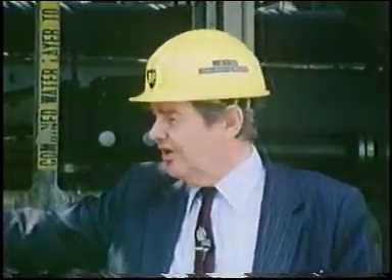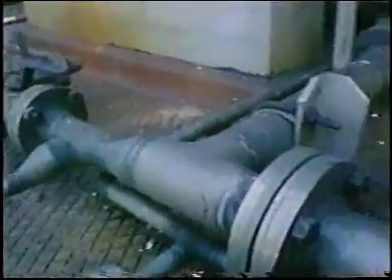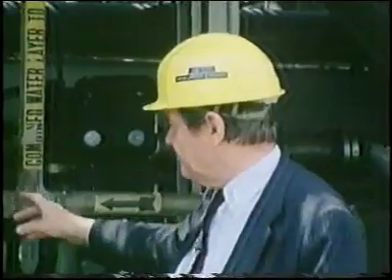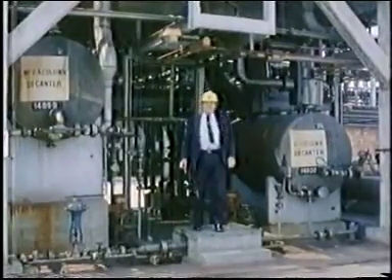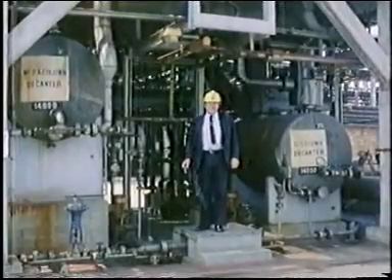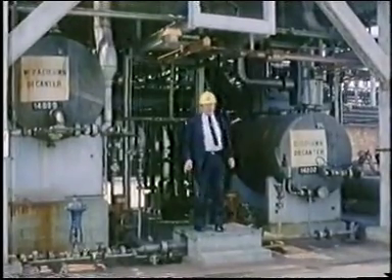The lower aqueous layer, with a few percent of ester and alcohol in it, is pumped away along these pipes to a distillation column in the next structure to recover the ethyl alcohol, which passes back to the reaction system. The upper ester layer, containing about 5% of water, is pumped by a pump at the back, a portion of it going back to the top of the distillation column to suppress acid distilling, and at the same time to remove the water of reaction. The excess ester layer, which is our make, is pumped to that distillation column, which removes the alcohol and the water and gives us dry ethyl acetate as a bottoms product out of the column.